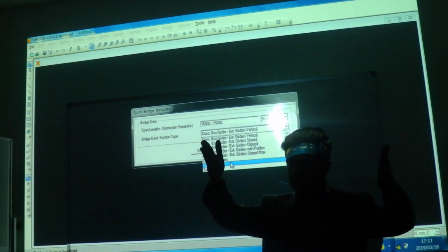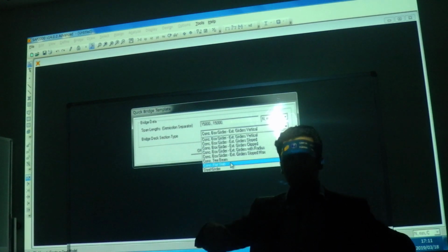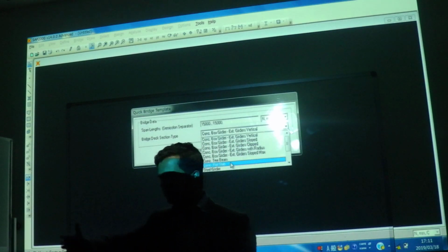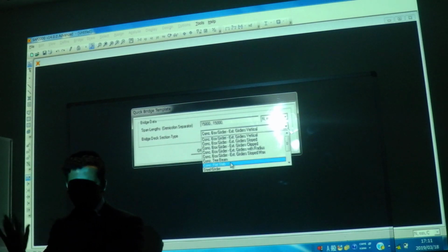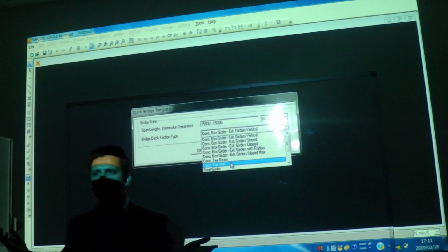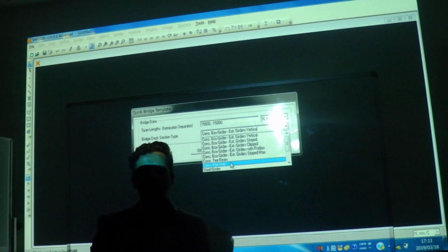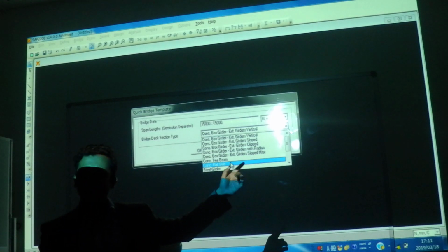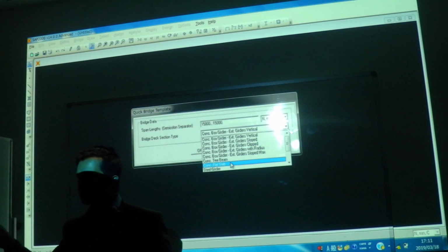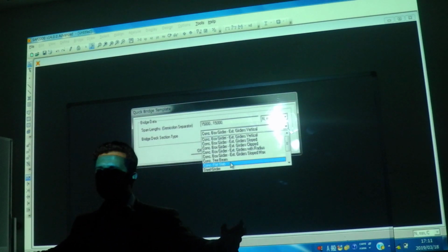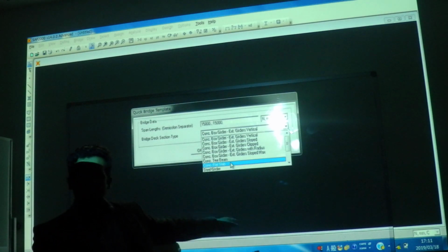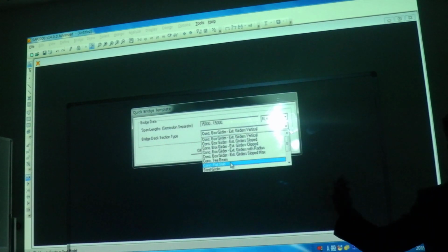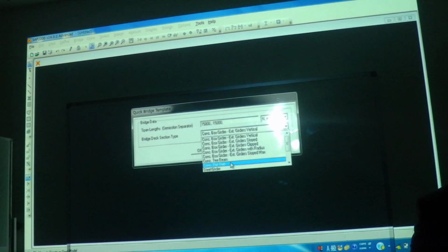For example, one bridge deck. Deck is the full assembly of girders and slab. If I put one deck here, another deck with the same span here, another deck with the same span here, it is just like 3 simply supported beams. So I'm just increasing my work. But if your bridge is a continuous bridge, like the example I gave you next to the theme, a bridge with a curve, the biggest span, continuous. I made a diagram here if you remember. In that case we can have 3 spans, so we can use this one.